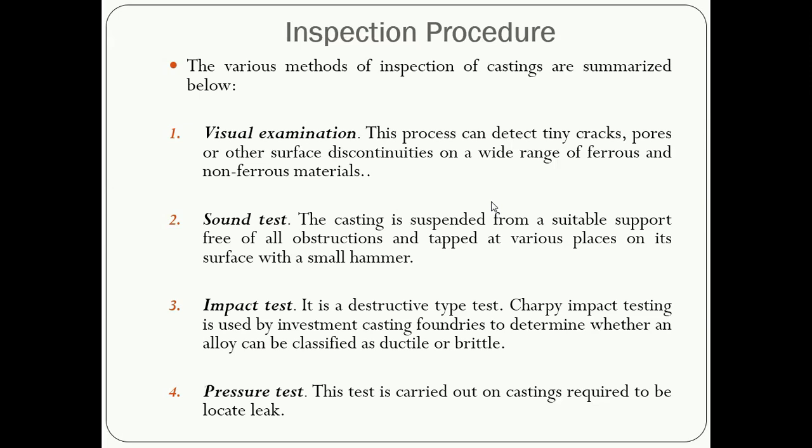Sound test is also very important. That test anybody can perform. We can perform that test in our home to check whether the marble which is fitted on the floor in our home has been supported properly from the bottom side or not.